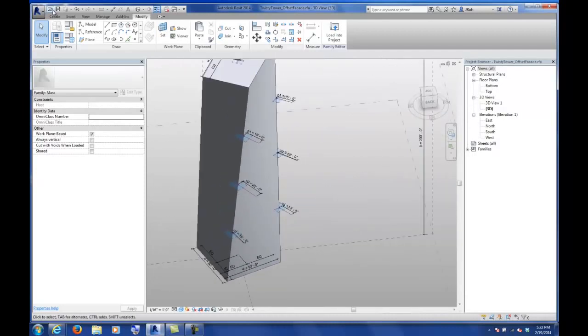Now, when you're making these kind of offsets, because it takes a lot of time to set it up, I would only do your extreme condition. Right now when you look at this, you're probably thinking, oh, this looks like great supports coming off your facade, and I want to show every single support. If you do that, you're going to take forever, and there are other ways that we can accomplish that in the future. But you really want to concentrate on what's going to make the form of your particular surface. So my extremes are the endpoints and then the midpoint, because I want a different kind of curvature at the mid. Obviously, if I just wanted to concentrate on the endpoints, I would just do the ends, and I wouldn't have so many points.